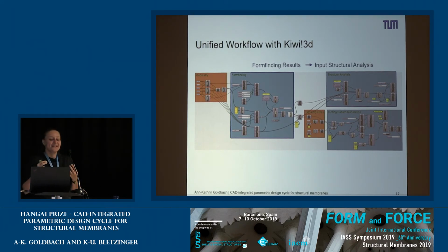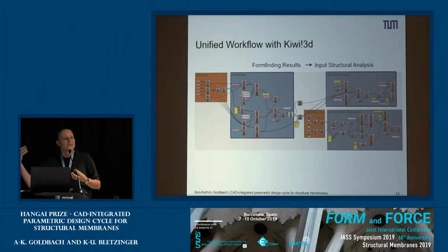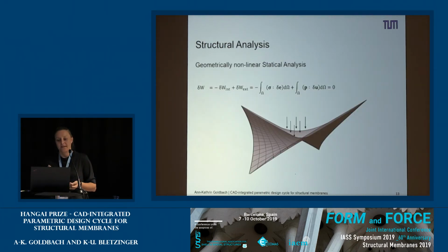And as you can see, if we were to change something in the geometry on the very left side in the orange box, like make the whole thing a bit bigger or a bit smaller, I can forward these changes to the next analysis because they are all linked together. So looking at the mechanical side again, what I mean by structural analysis is geometrically nonlinear statical analysis. And here we just have a virtual work expression just to put you in the setting that we're working in.